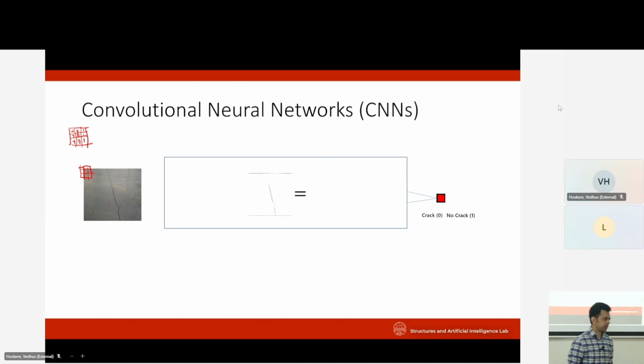You move the window. Yeah. So in my extreme case, even if there's one jump, then it's a crack, right? But if you want to make it more sophisticated, you can count the number of jumps and have some threshold. If it's more than this many jumps, then there's a crack. So you can have some simple logic to process this image, and then you decide if there's a crack or not. Similar to that, people build many algorithms that are more and more sophisticated.